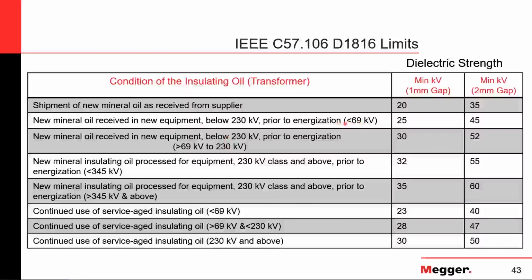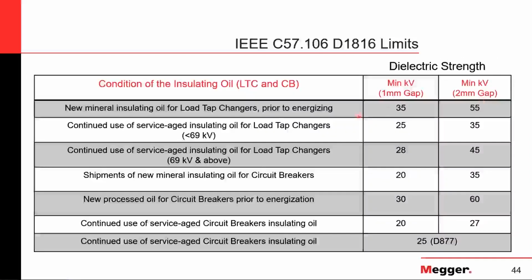So I want to summarize everything we just discussed with an easy to remember do's and don'ts list of when we are performing dielectric breakdown voltage testing. For the do's, of course, use the proper procedure recommended by the standards depending on your application. Be mindful, like I've been saying, I don't know how many times during the presentation, I cannot stress it enough. Be mindful of cleanliness as well as the ambient conditions when sampling.